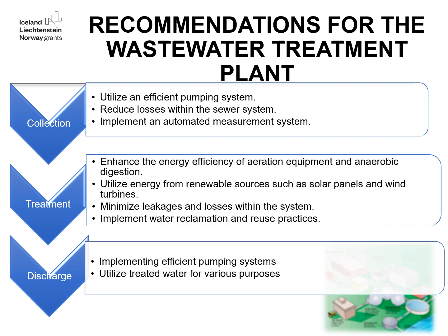Among the options presented are using an efficient pumping system to minimize energy consumption, improving the energy efficiency of aeration equipment to reduce energy consumption in wastewater treatment processes, optimizing the anaerobic digestion process to efficiently use organic matter and produce biogas, which can be used as an energy source, and integrating renewable energy sources into the treatment plants, such as solar panels or wind turbines, to reduce reliance on traditional energy sources. These strategies contribute to increasing the sustainability of wastewater treatment plants with a positive impact on both the environment and operational costs.